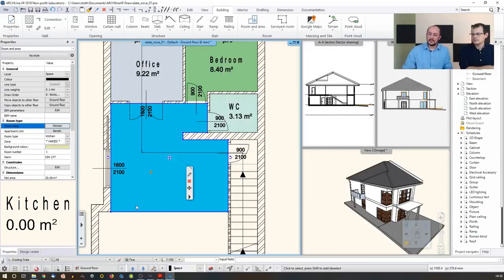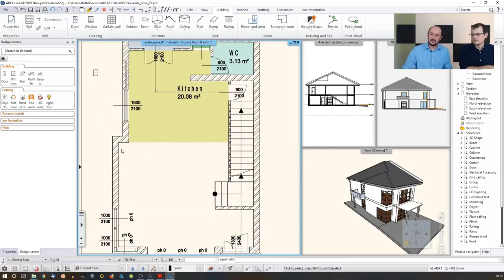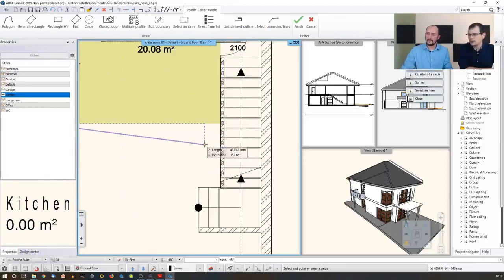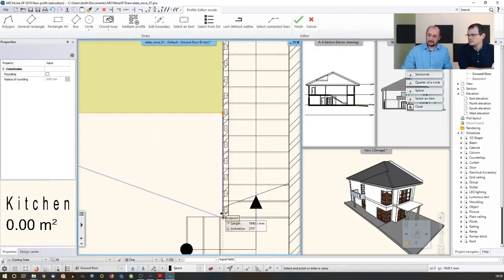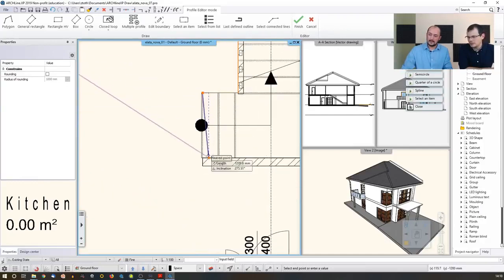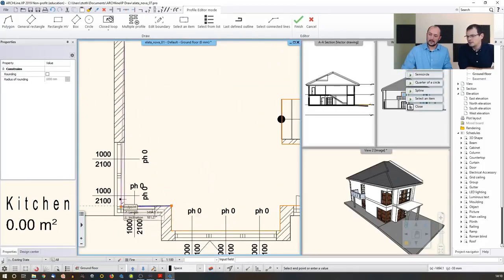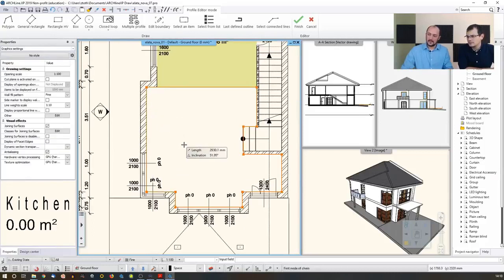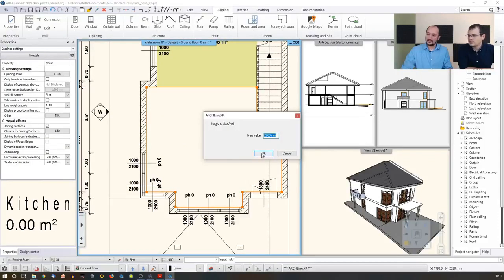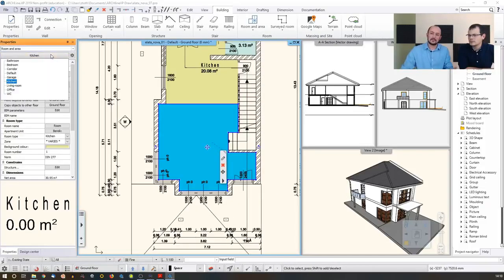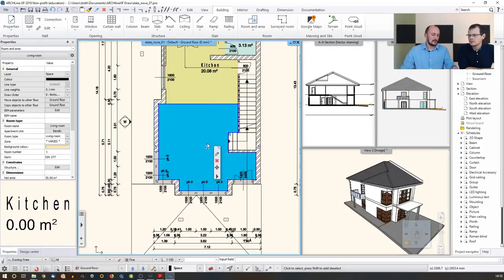And I just quickly remake this whole thing, but this time with this part, which will be the living room. So I just use the same tool again. So that part is going to be chopped up into a kitchen and the living room. And I assume, like I said before, that you can later on manually change the contour. The bottom line is that here you have manual control over what you are going to include and exclude in a certain part of a room, and assign it to be, in this case, a living room. Yeah, that's right. So it's just again enter and accepting the height. And now a room is appearing. Well, I didn't change the type, so I just change it to living room, for example. And if I need to, I can also change the text, how it appears.